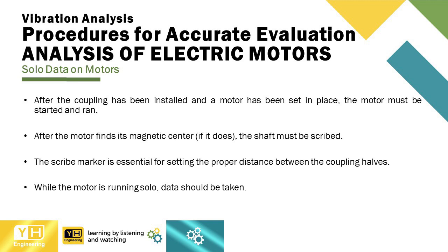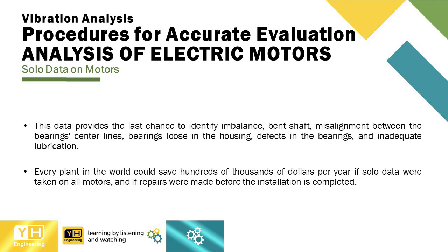While the motor is running solo, data should be taken. This data provides the last chance to identify imbalance, bent shaft, misalignment between the bearings' center lines, bearings loose in the housing, defects in the bearings, and inadequate lubrication. Every plant in the world could save hundreds of thousands of dollars per year if solo data were taken on all motors, and if repairs were made before the installation is completed.